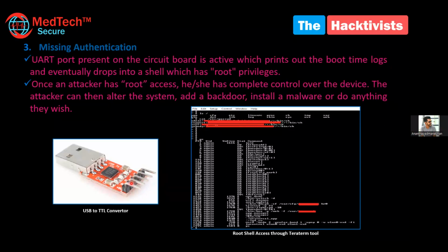So this will also have a receiver and transmitter. So how similarly will the UART communicate with the device? We'll connect the receiver of this device to the transmitter of the UART, and vice versa, the receiver and the transmitter. So we'll connect and we'll use a UI tool called Teraterm for analyzing or finding out the data communication.